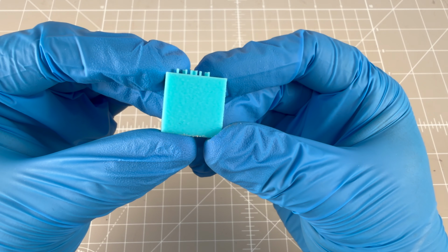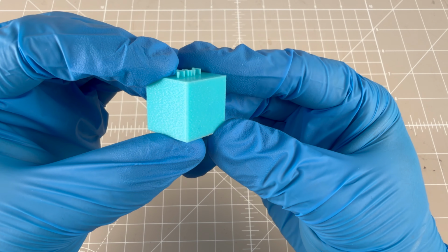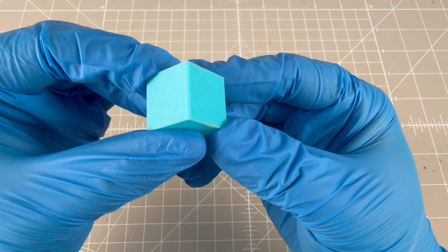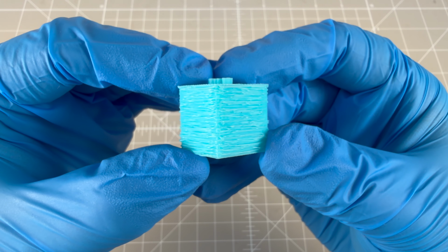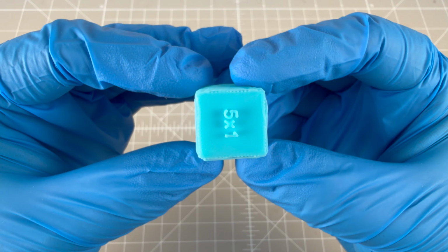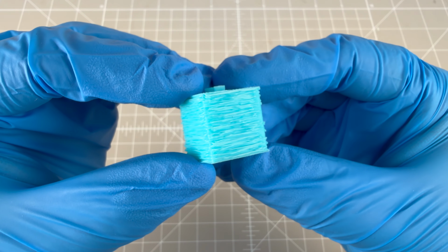When looking at the cube with the smallest settings, 0.1 for both point distance and skin thickness, we see a very subtle texture that's almost imperceptible but can still be felt. At the complete other end is the cube with a point distance of 5 and a skin thickness of 1. The lines look haphazard and are long, which you would expect when the point distance is set to 5.